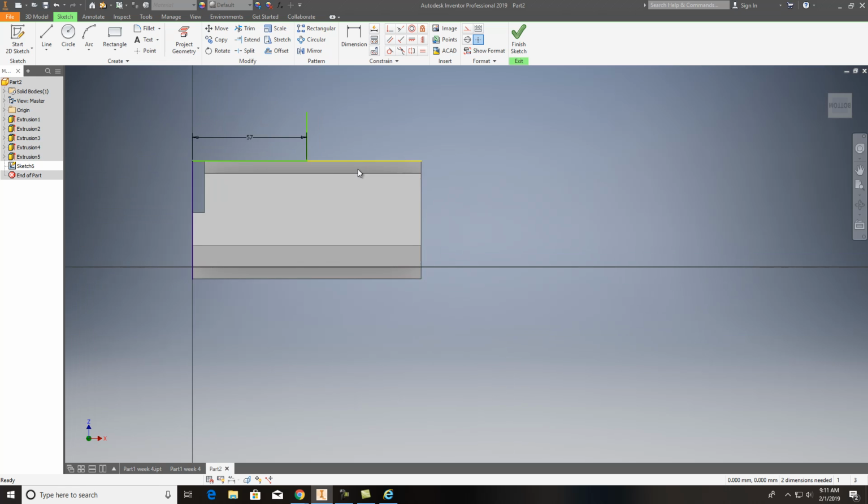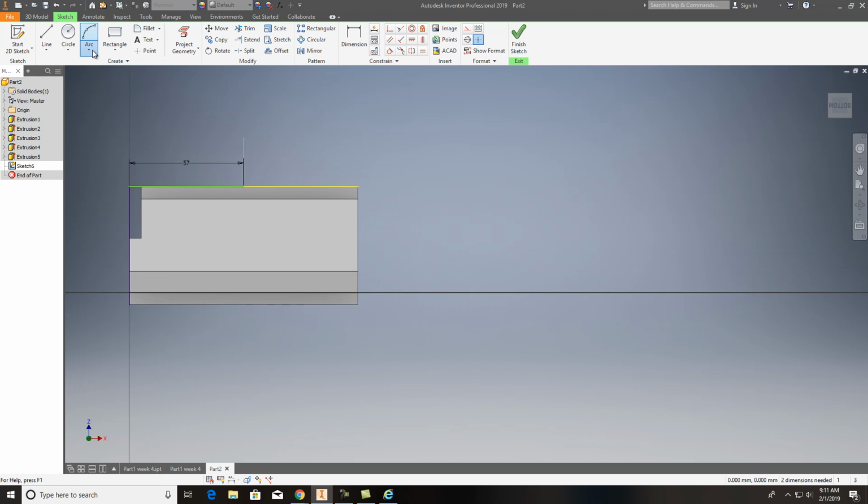So at that point right there, coming to right there is going to be that radius. And here, there are a lot of things you can do. You can hit a 3-point arc. You could hit there to there, and then type in 60 for your radius. And you see what I did there wrong. You can type in 60.